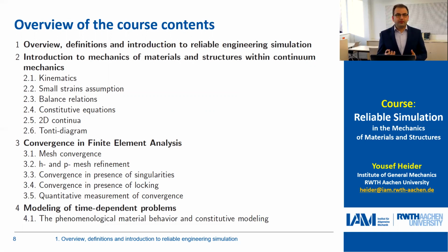Some of this information could be found in other courses, but here we address these issues in the context of reliable models. Then we will talk in the third section about convergence within finite element analysis, some issues like the h and p mesh refinement, the mesh convergence, and how to quantify the convergence.